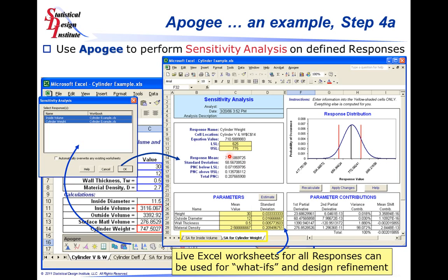Now, if we make a normal distribution assumption at this point, and let's say that we do have a normal distribution with a mean of 710.58, a standard deviation of about 58.57, and if we compare that dispersion with our specs of 625 and 775, this would indicate that the area in the tails of this normal distribution outside of the spec limits is going to be non-complying product.